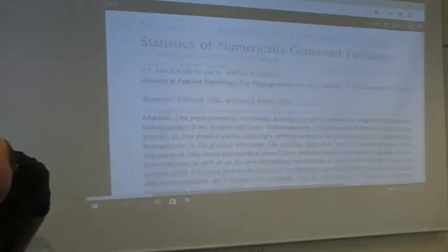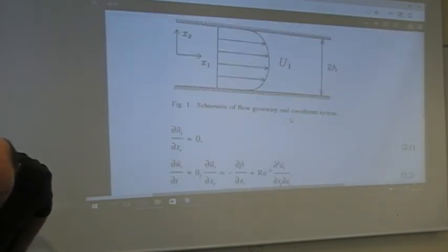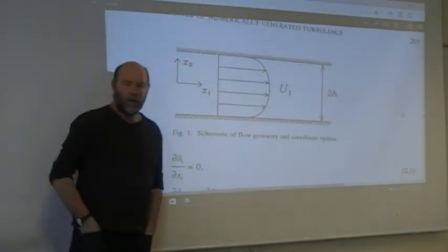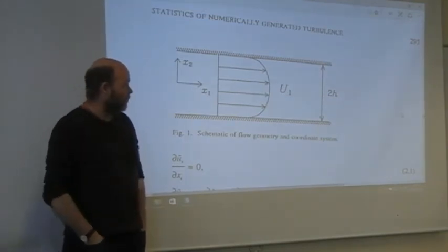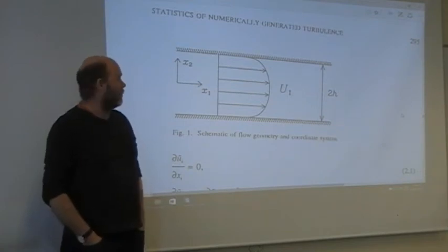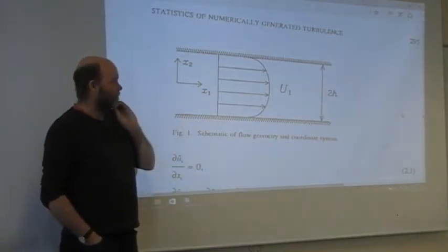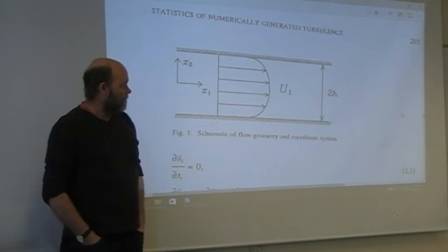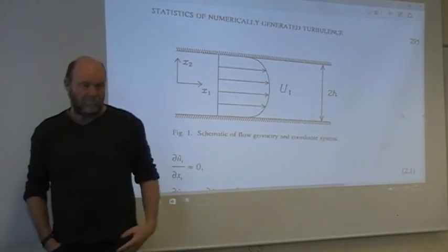As a case, we look at the simplest geometry possible. So we have this one. It's a two-dimensional steady-state problem. The turbulent process flow between two parallel plates, and that's it. So this is, of course, then a one-dimensional problem. If you use turbulence models, you just simulate across from wall to wall here, finding some turbulent velocity profile, and done.